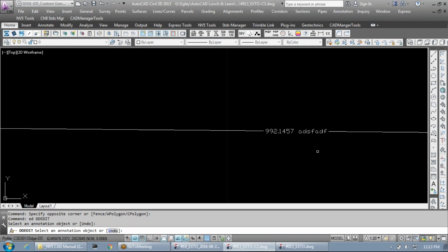And sheet set begins at plotting. We expand it to handle our sheet numbers, right? We don't want sheet numbers on each sheet being just regular text. That should be a field from our sheet set, match lines, and now we can populate all kinds of custom properties. So you're really going to see this grow here. So become proficient using the sheet set.